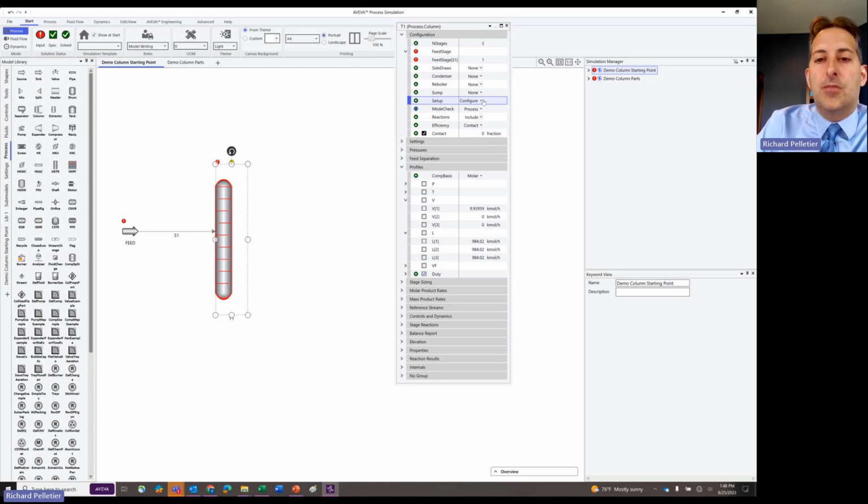So right now, no separation is occurring. It's using very simplistic equations to solve all of the column mesh equations, all the different equations that it's trying to solve for all the various properties. So we're trying to populate some initial values so that when we try to do the more rigorous calculations, it has these starting points to start from. It's more likely to solve.